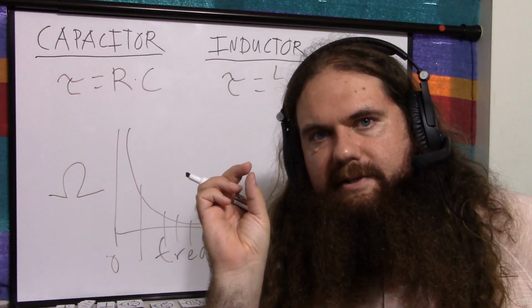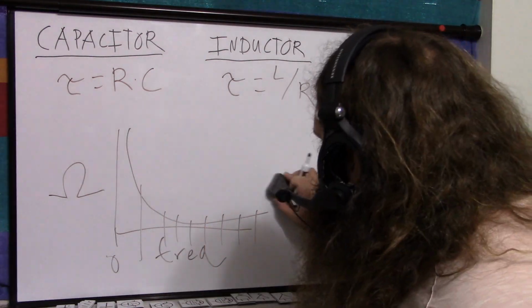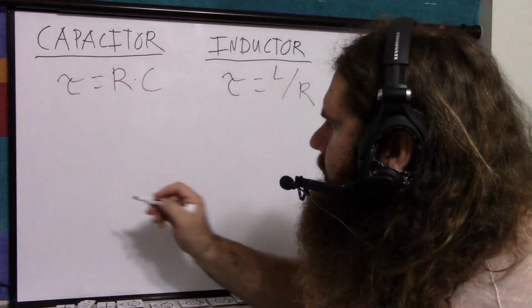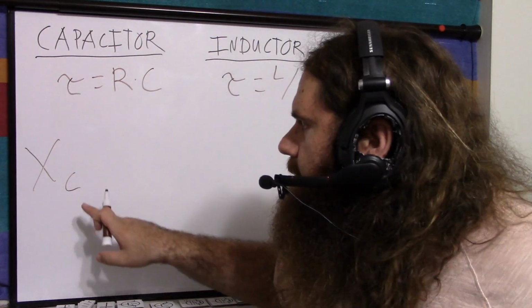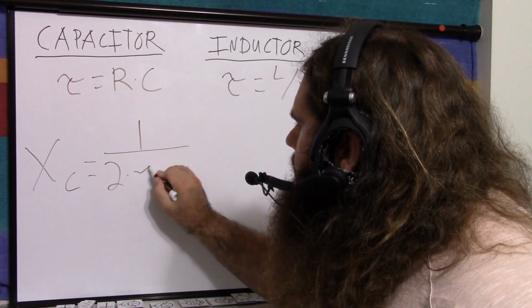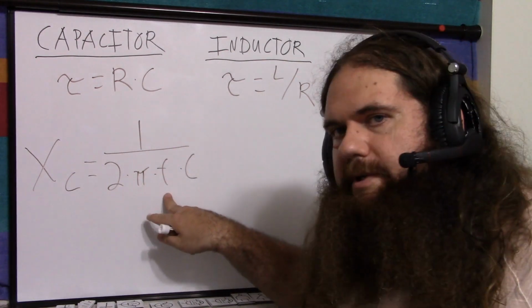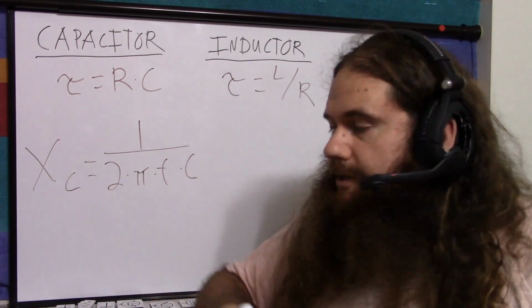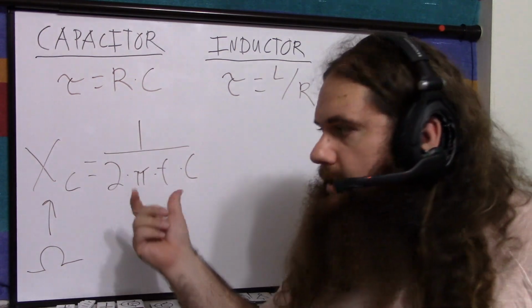It's acting as less of a resistor for that frequency, and then you get your Fourier split and all that stuff. So a capacitor has greater reactance, which is usually written as XC. The reactance, because they wanted to write X, I don't know. Reactance of the capacitor equals 1 over 2 times pi times frequency times the capacitance. As the frequency gets bigger, the denominator gets smaller, which means the reactance, the effective ohms, gets smaller. Higher frequencies, less resistance.